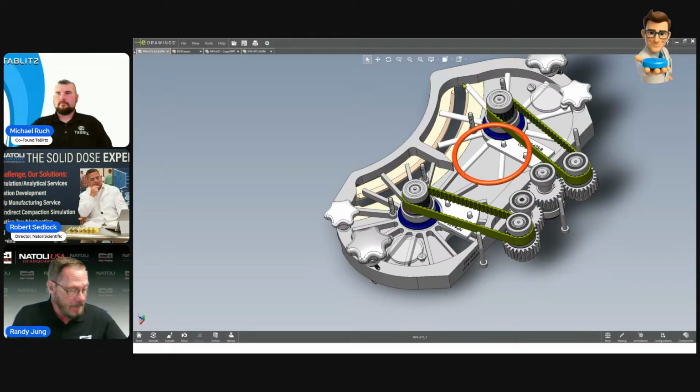Right. So I can go to a smaller paddle, in terms of design, a small round. So now I don't have this up and down motion. I'm not aerating the powder. I'm not moving it very much. I'm just gradually moving it into the die. It's a very relaxed environment. The powder responds much better in many cases. And again, if you have a powder that doesn't flow well, I might need this big plow design. If I have a powder that flows really well, I might need this little wire design.